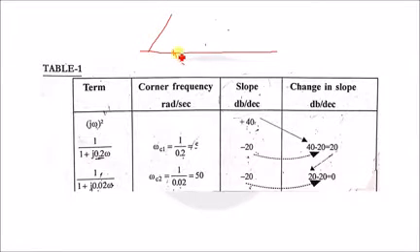If I do not add anything here, let's say it is 0 dB, then it should continue with the same slope, that means it should continue with 40 dB. But before continuing, at this frequency, it added a minus 20 slope. Mark my word, it added a minus 20 slope. That means with plus 40 it added minus 20, so the slope now becomes plus 20.